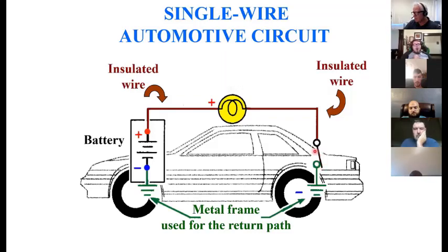Once that door is in a position where this switch closes, the current leaves, goes through the load, it gets to here and it's marked as going to ground. You notice that this is also at ground. So it's grounded to the frame of the car. And that allows the frame of the car to be a conductor. So the current flows through the load, through the closed switch, into the chassis, along the chassis back into the battery. So there's my continuity. It doesn't stop here. It's actually common or connected to here.